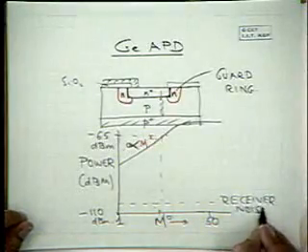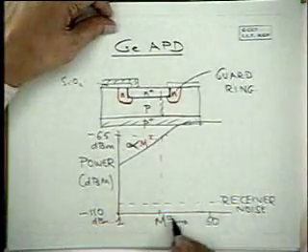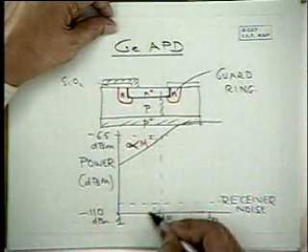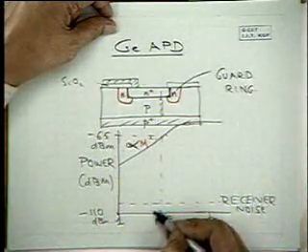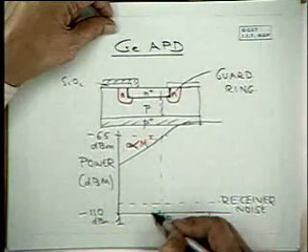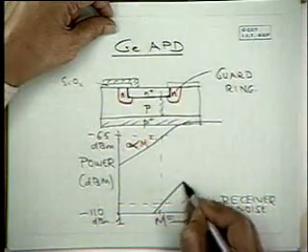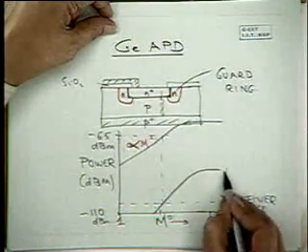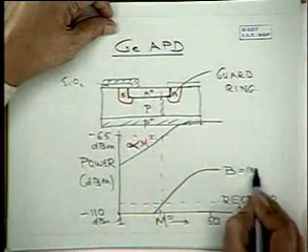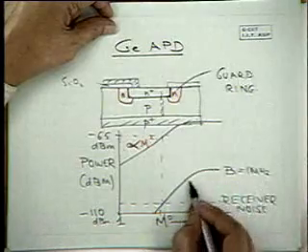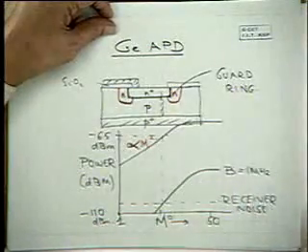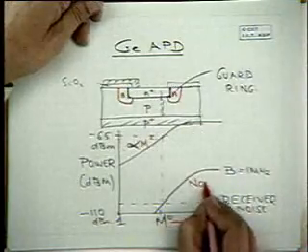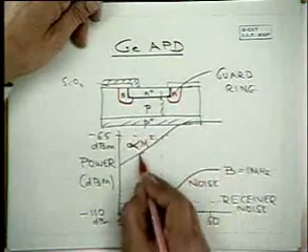This receiver noise is always there, independent of the device. Now, as you increase m, the avalanche multiplication noise goes up, something like that. So this, say for a bandwidth of 1 megahertz, is the avalanche noise, and this is the signal.